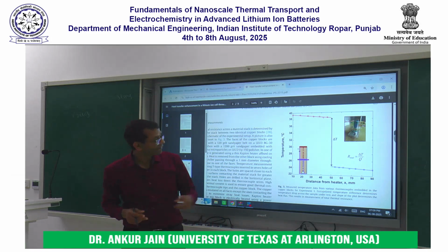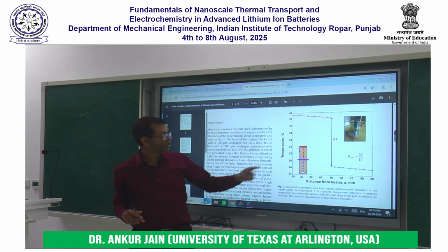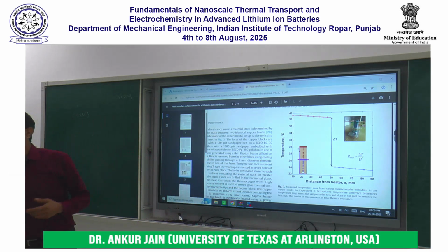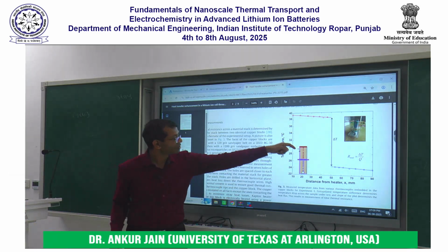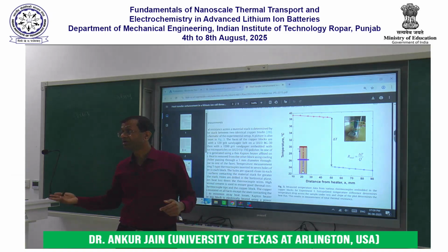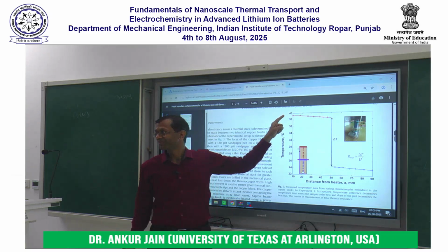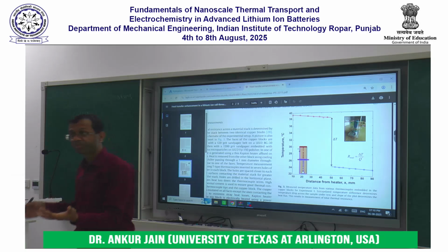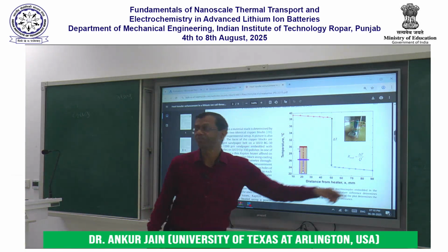The best way of finding out how much heat passes through this is by using the copper blocks as a reference. How much heat is passing through the copper blocks? At the top, the amount of heat passing through the copper blocks is given by K copper multiplied by dT/dx, the slope of this line, right? The heat passing through the bottom copper block is given by K copper multiplied by the derivative of temperature in the bottom block, right?